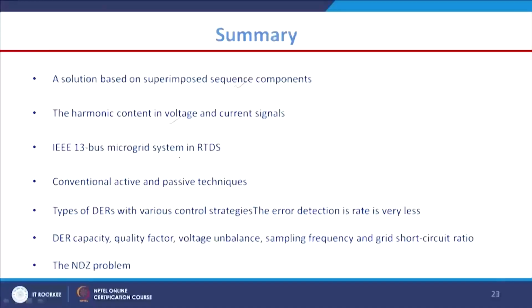By using a least error square based technique, we can always extract the fundamental voltage and current phasors. We took an IEEE 13 bus system and also simulated an IEEE 34 bus system, where we also considered tie line switches, single pole tripping and high impedance faults. Different islanding and non islanding situations were created, and the corresponding results are tabulated and figured out.